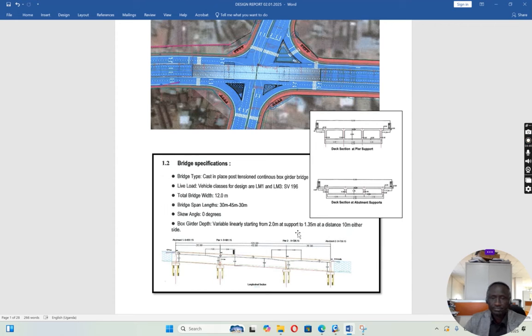So those will give you almost this requirement they're indicating here, like 2 meters, 1.3. What are the span-depth ratios you consider when you are coming up with the section? So at the preliminary stage, you have to do all those preliminary checks to give you where to start from, and then using iteration during design, you are able to refine and get adequate sections.